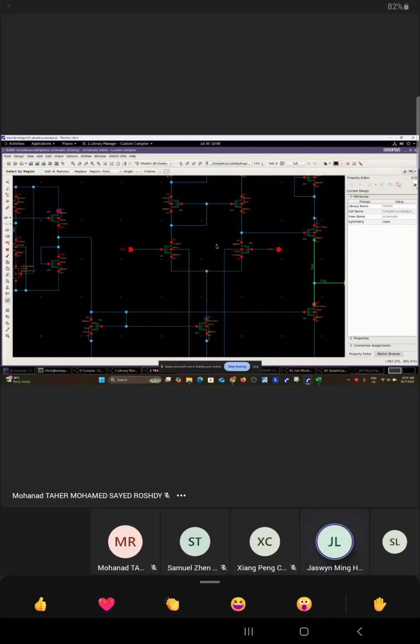And then you notice that you have a second stage. Second stage amplification means that this also inverts one more time. So if you put V in minus here, it inverts to V out plus, inverts again to V out minus. By right, this should be your V in plus. Plus, minus, plus, so it should be the other way around. If you look at the lecture note of your day 2 or day 3, they mention that if you implement 2 stages, you invert twice, double negative. So here you should connect to V in plus, and then this one should be V in minus. That should be the other way around.